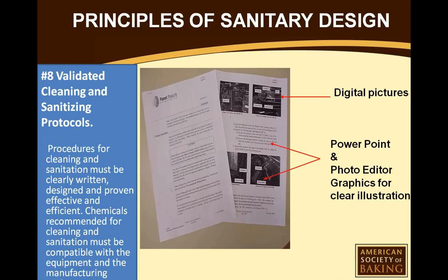The equipment supplier's other areas to address are what needs to be cleaned and how. Is it a wet clean? Is it a dry clean? What cleaning processes are used, and are there restrictions on sensitive components, particularly in the area of sensors or maybe electrical devices? How are your parts stored? Are they safely removed and stored during the cleanup cycle? Have you developed a parts cart? What maintenance tasks are required before and after cleaning and sanitation? And have some consideration for how it will be sampled for microbial, allergen, and ATP. All of these need to be included in the validated process.